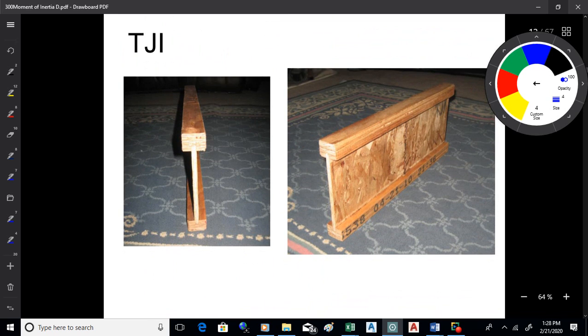Okay, now in the old days for houses, they just used 2x for floor joists. 2x8s and 10s, I think, primarily 2x8s a lot, I think. I'm not sure, but I think it was 2x8s. But nowadays you use this TJI. They're cheaper to make, they're lighter. They're kind of this press board for the web, and then they have these small flanges. And it's just cheaper and lighter.